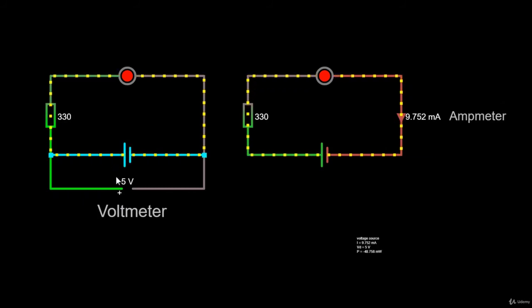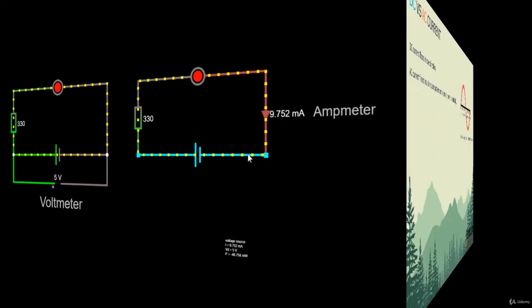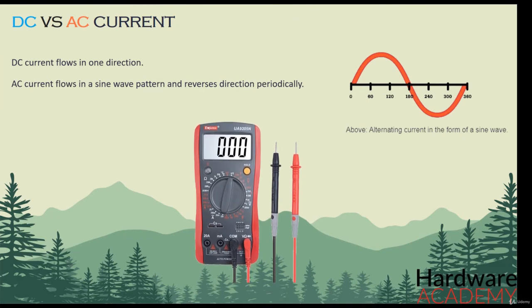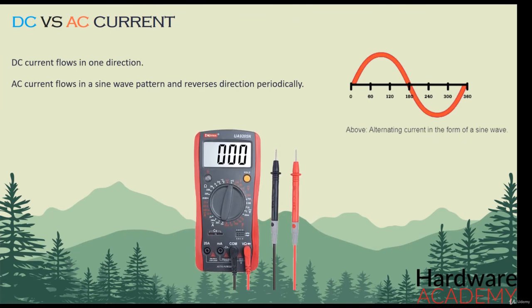component. In case you want to measure current, you need to place the two legs, which in engineering terms are called probes, in series with the circuit. So you have to break somehow the path and place the two probes in series so that current can flow across the multimeter. It makes sense, right? And most digital multimeters can measure DC or AC current no higher than 10 amps.